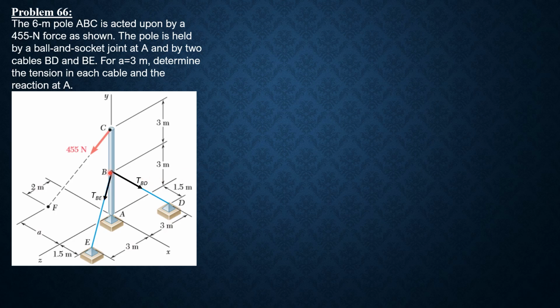Then we will define all these tensions in vector form as well as this force and transmit the component reactions at D and at E. For TBD at D, for TBE at E. You can actually transmit it at B, but because there are so many component reactions at B, then it might be difficult to visualize the components.